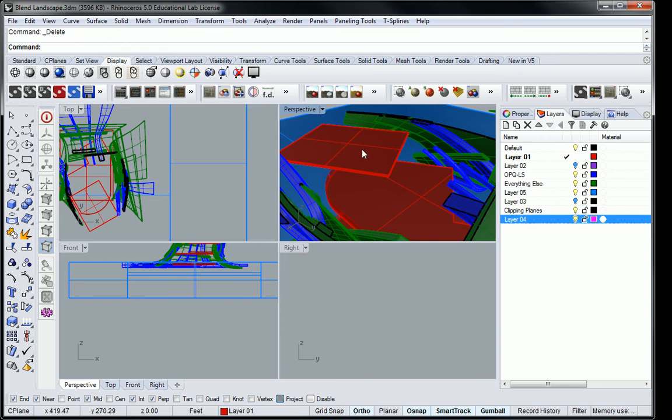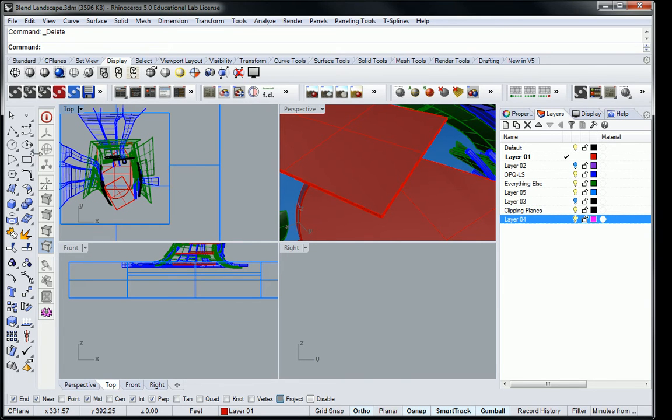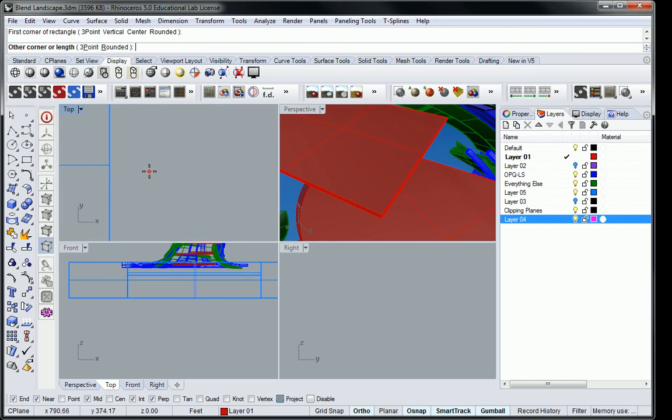Anyway, so that basically, to me, what that means is this. We can create a stair, a schematic stair, very, very simply by basically drawing the plane. So you can just do a rectangle, say 4 feet. Actually, let's just make it 15 feet by 4 feet. Ah, crap, did it wrong. That's going to be 15 feet by 4 feet. It looks like that. That's really, really small.